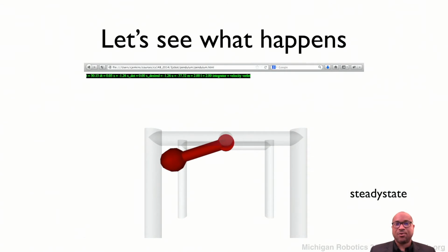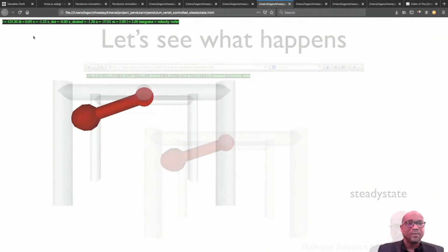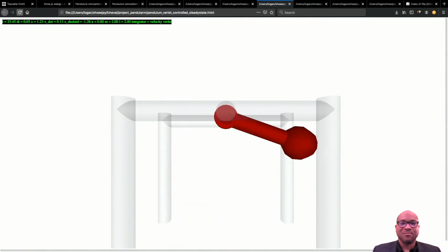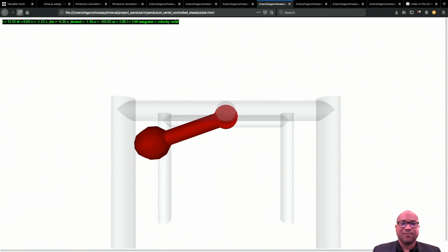And so I can show you. Here's an example of a pendulum that I tuned with respect to both its proportional and derivative terms. All right, so let me reload this. In this case, I have the system here. I'll let this pendulum swing, and then after the pendulum swings, I'm going to start the servo, and the servo gets to where the desired location should be. It actually gets there pretty quickly, pretty reasonably. But one thing that you'll note is that we don't quite actually get there.